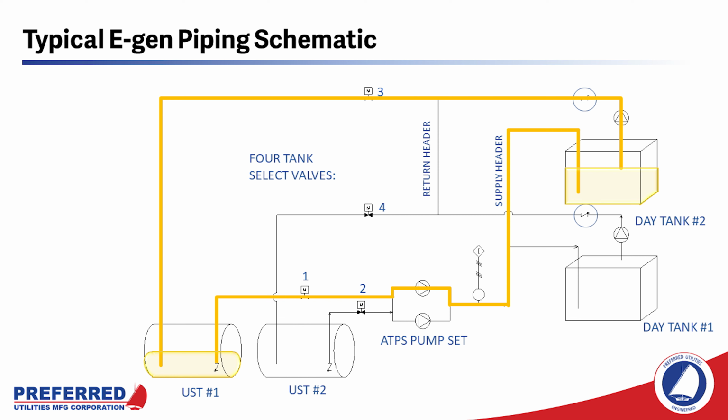So what I'm going to show you now is that you can use that pump and pipe sizing program also to make sure that your return piping is going to work with the system. Whenever you have an above ground storage tank, you're going to see a return pump on each of your day tanks, because you need to be able to evacuate that day tank if you start to overfill it.